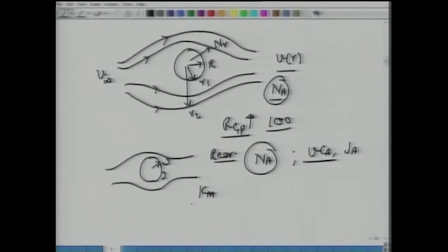we have the flux now, which we can write as diffusion flux NA equals mass transfer coefficient times some concentration difference, where del C is the concentration difference between Cs at the surface and C infinity. Okay, so we are trying to make a case here. What is the motivation of mass transfer coefficients? Why do we have to define this quantity, and where can we get away without defining this mass transfer coefficient?